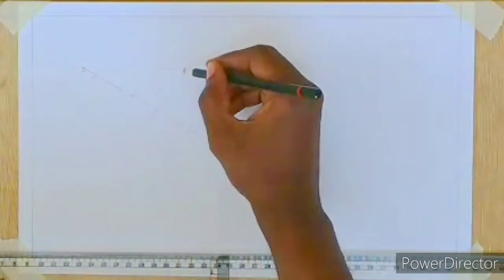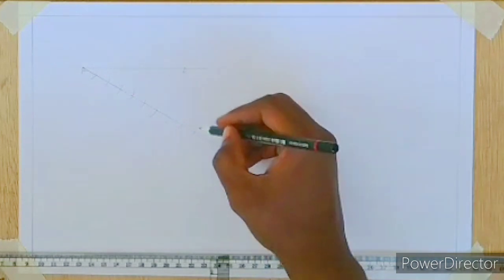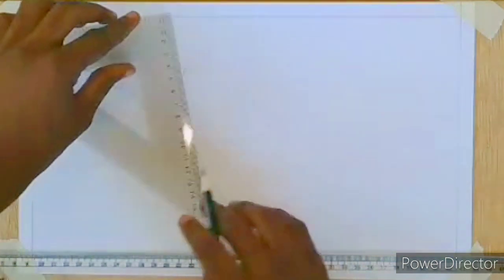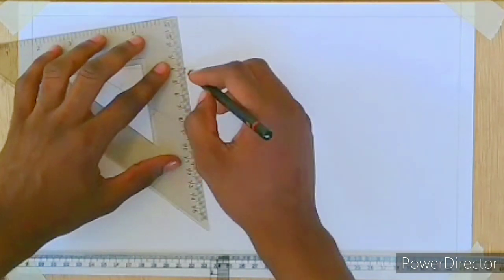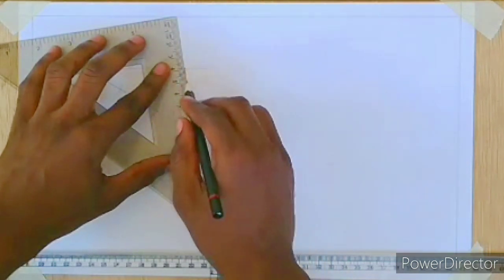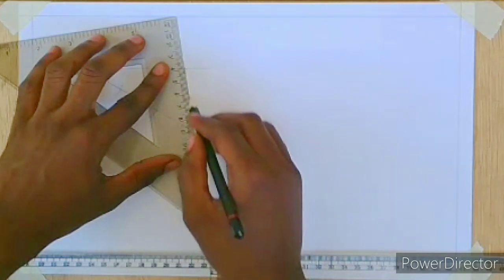This time you can pick any of the set squares. You can pick the 30-60, you can pick the 45. I've chosen the 45. Then, from this point here to here, you draw a line to attach them. So like this. Should be exactly on the point, because the slightest change will make a whole lot of big mistake.